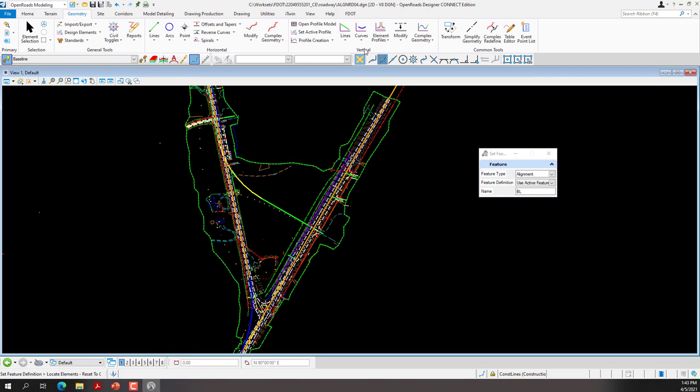There's a table on 3.2 that we're going to use for design intent, which says the design geometrics and criteria is from the FDOT Design Manual, or the FDM, Part 2, Chapter 210. Design speed will be 45 miles per hour. The facility that we'll be using is low speed desired length.